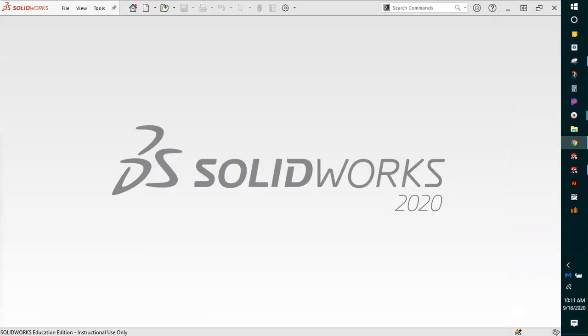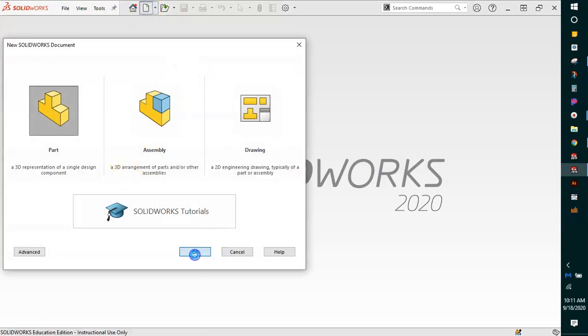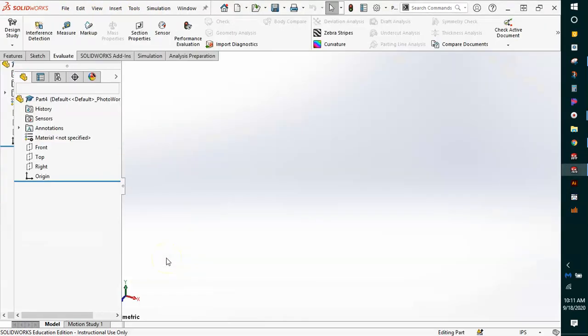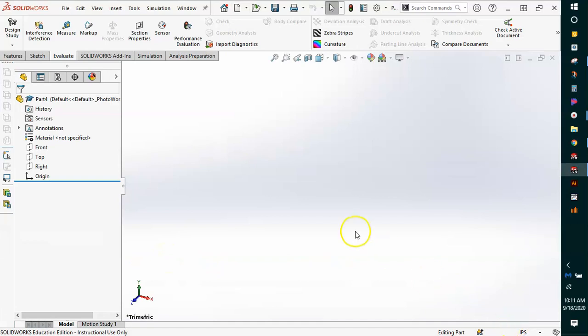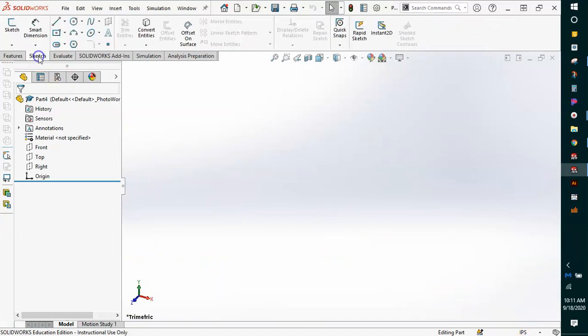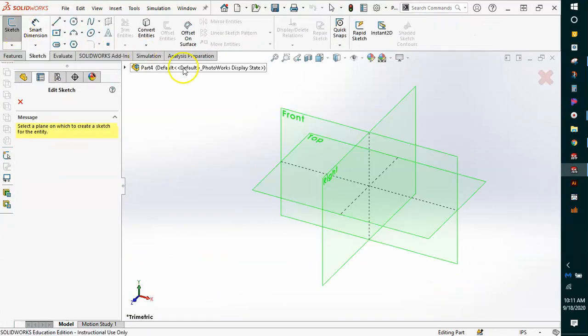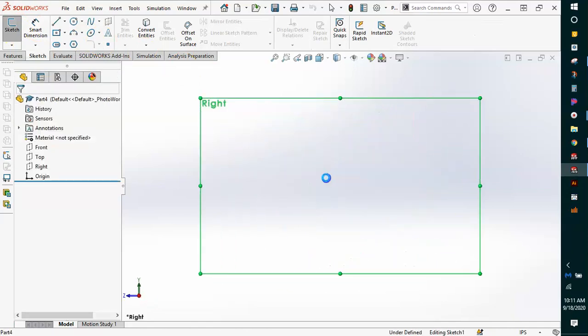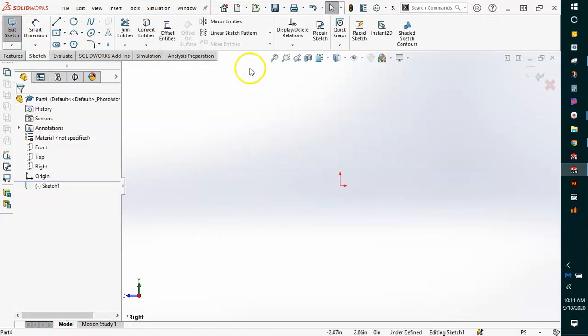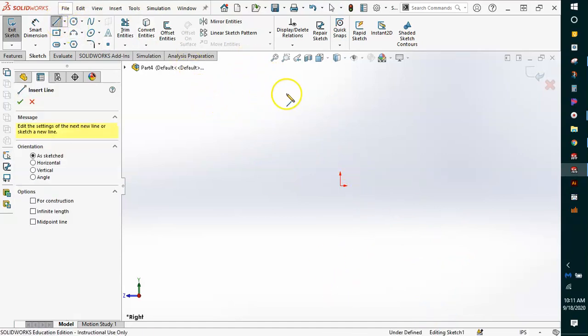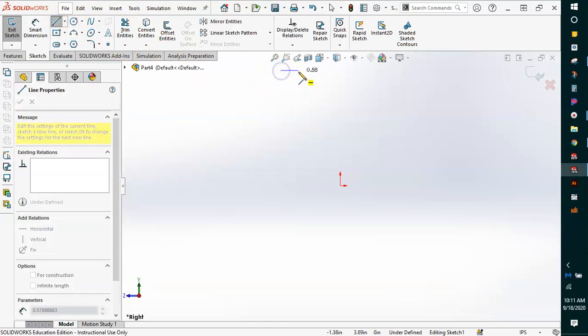So I'm going to pull this to my other screen if you haven't done so already. You can create a new part in SolidWorks, and we're going to make sure our units are in IPS. My computer defaults to that, so I'm good to go. I am going to be sketching on the right view, or the right plane. And first, I'm going to sketch what I see here, which is a big angled piece. I'm just going to use my line tool, and start somewhere up here, and just draw what I see, and then I'll worry about dimensioning it later.